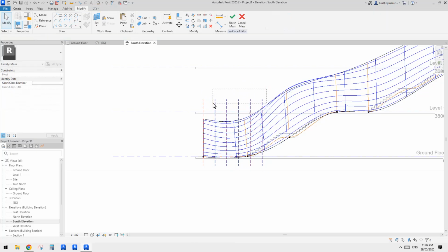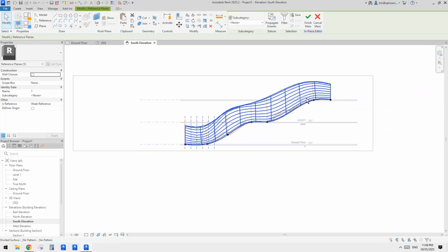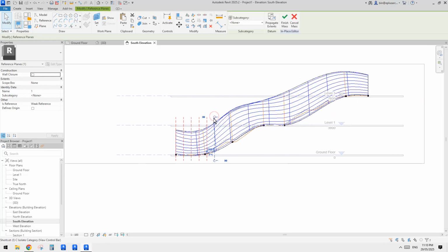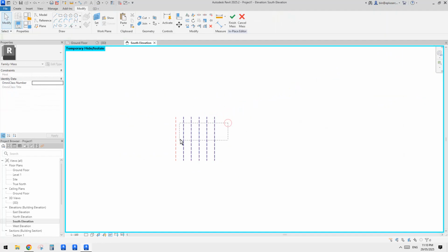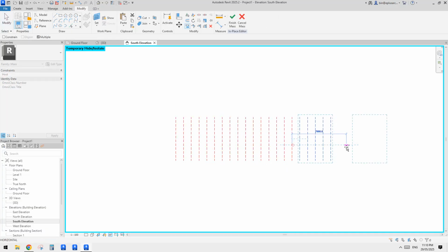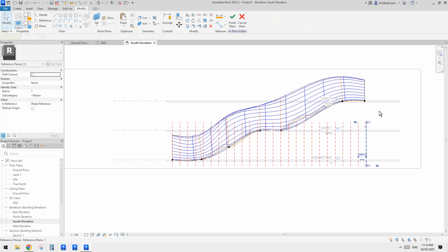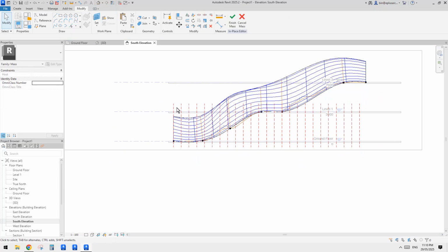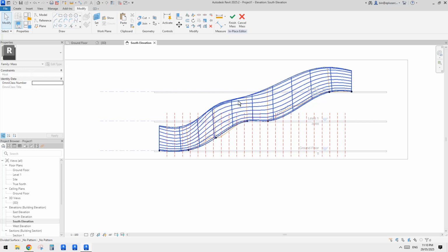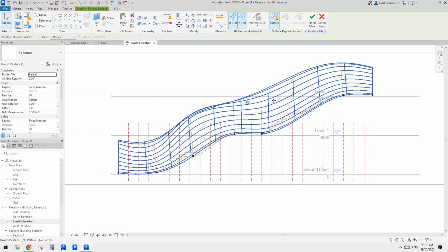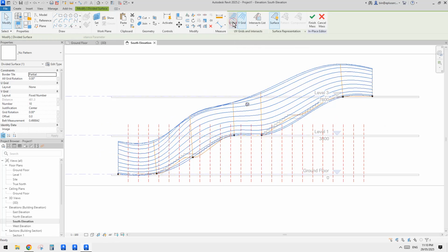and maybe just select our type. Type IC. So we can just copy more. I think that should be enough. HR. Yeah, that's enough. We don't need this, and maybe not this one. Now we select this divided surface, go here, turn off the U grid. So now we no longer have those almost vertical grids.